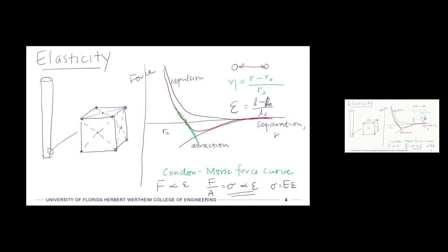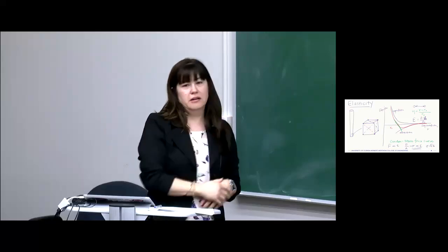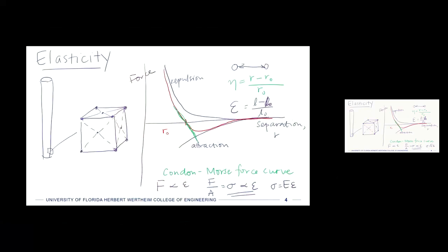All right. So this is really helpful, but unfortunately, we know from other undergraduate classes, from pulling on materials, that they don't fail, typically. Ductile metals don't fail in a tensile fashion. If I take a piece of aluminum or steel or something like that, and I put it in grips, and I pull on it until it fails, and I open it up and look at that failure surface, I'm not going to see a straight line across, right? So we can't get everything we need from thinking about these 1D problems. So we have to think a little bit about shear as well.